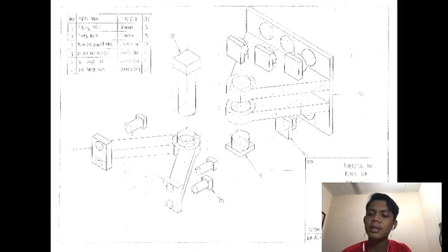The second one is the hex bolt M10, which connects fitting 1 and fitting 2, and it is paired with hex flush nuts, of which we have 5 in total in this mechanism, and it is also made from stainless steel. The last one is a hex flat screw which connects fitting 1 with the wings. In this case we have only 30 also.